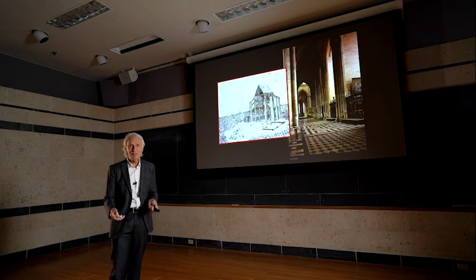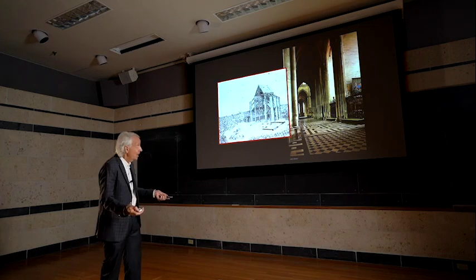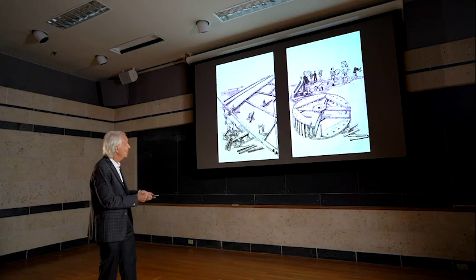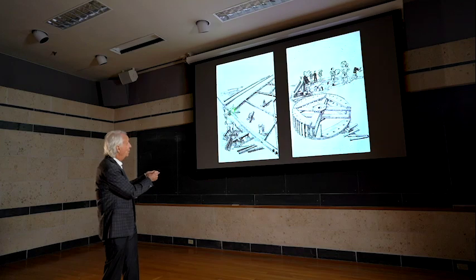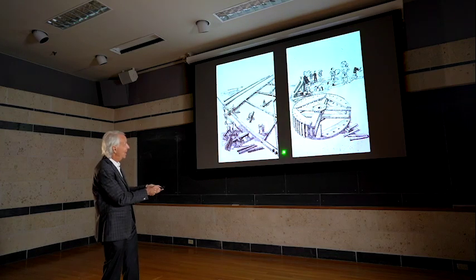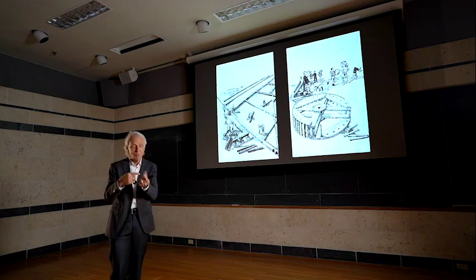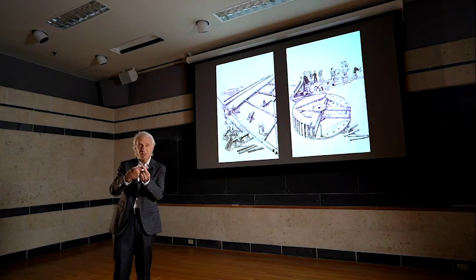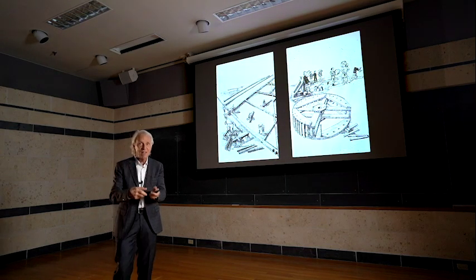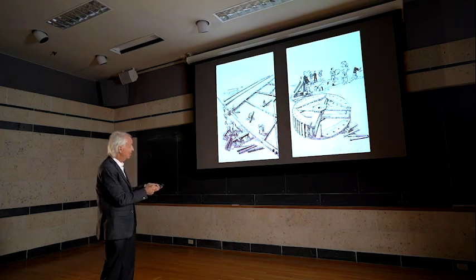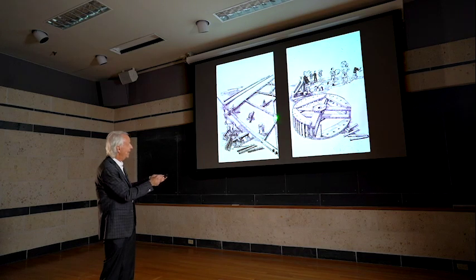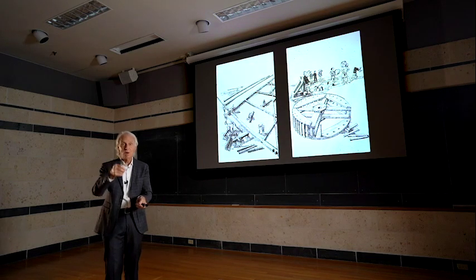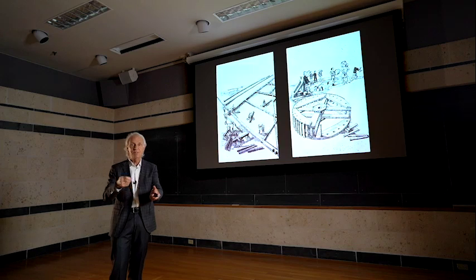This incredibly heavy truss. So again, they had to have a building process innovation. They kind of prefabricate the truss down here on the ground. They have joints that are mortise and tenon, where they dig a hole and they stick a tongue through it and then they pin that connection. But that makes it so that they can disassemble it. They can assemble it on the ground and then disassemble it and take all those pieces up one by one and then reassemble it up at the top.